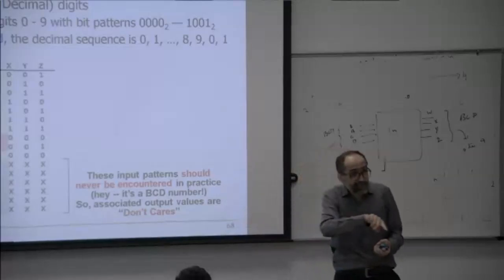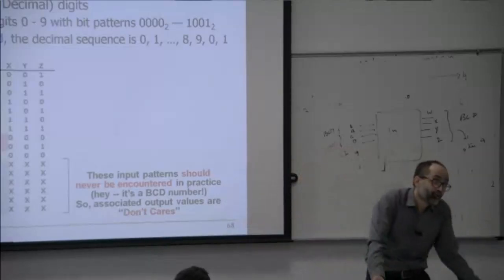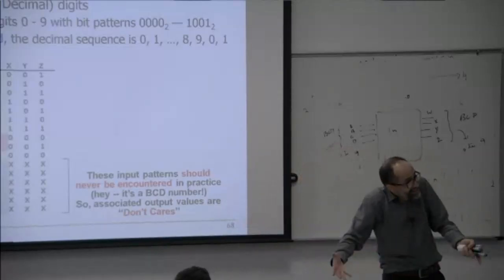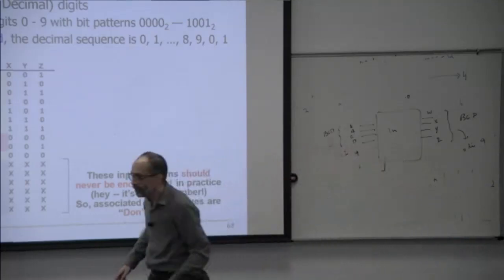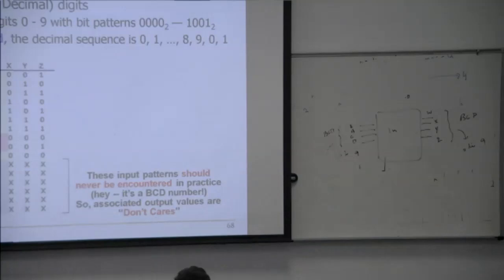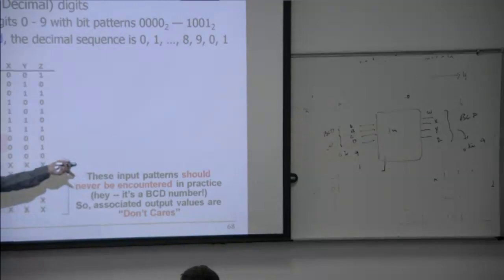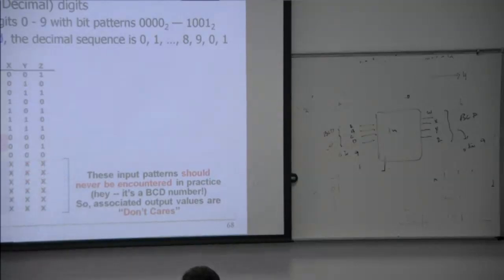But when the output is 0, automatically it is an overflow. When the output is 0, it is an overflow, because you add 9 to 1, there is an overflow. Got it? So now we can derive it from here. What is overflow? In this case, overflow is 1. What is overflow? W bar, X bar, Y bar, Z bar. We can directly do it without doing any minimization. Got it? So now, if you look at here, you know how to derive this function.